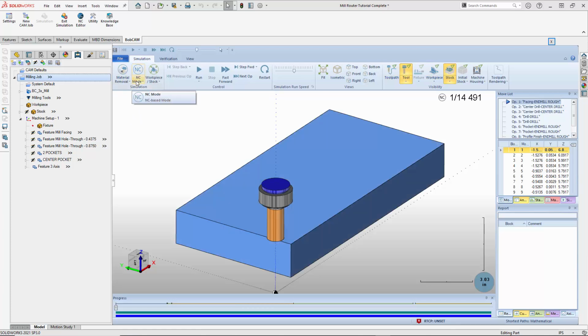The next section right here, this NC mode, time mode, or length mode, is just how it shows these movements inside the job. So NC mode is going to be like how you read your NC code, how you can see it go from where it's positioned, so your starting position, and then the next line you read is the next point that needs to be output. So with this NC mode, the biggest problem is anytime it makes a straight line, it kind of just starts at the beginning and then it's at the end. You don't really see the tool moving.